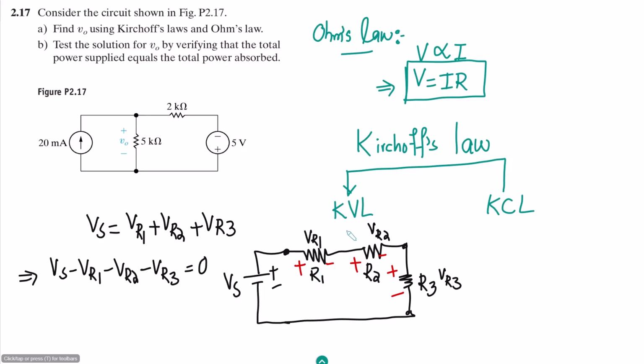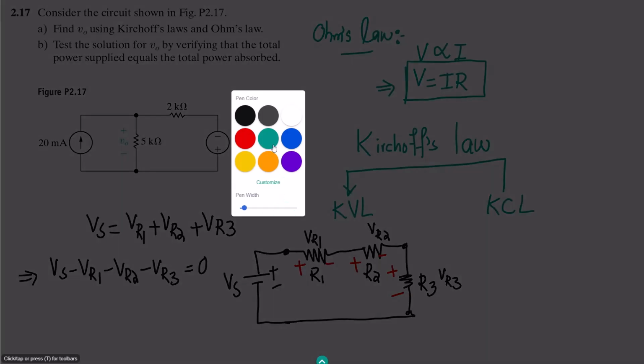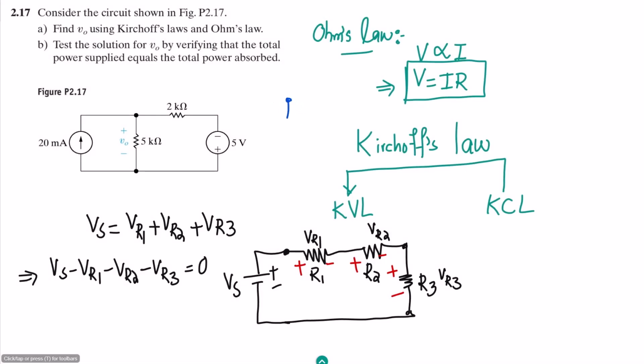Okay, so this is in this circuit. Suppose we have a branch like this one. Many people get confused here because of it. This is the ground one. Let me have here VP. This is, let me call it, a 1 kilo ohm resistor, and here we have this one negative positive 5 volt. So we can also apply the KVL here. As this one is the positive terminal, it can be interpreted that this is positive and the other terminal here will be negative.